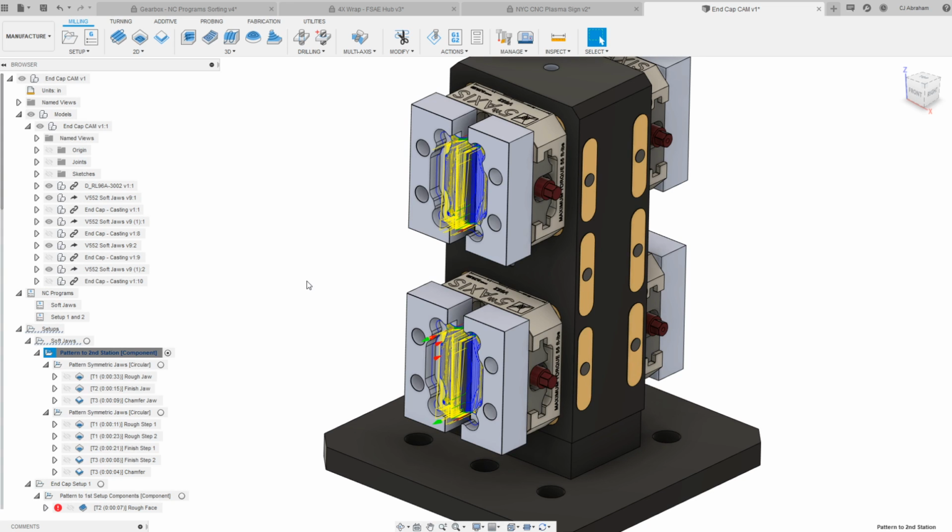Yeah, right. That is true. Oh, I'm sorry. It's hard not having your audio. So this is a case where, because this is all based off of one offset on the tombstone, you don't have to use multiple work offsets. You can just do a toolpath pattern and it will place the toolpaths in the correct position.